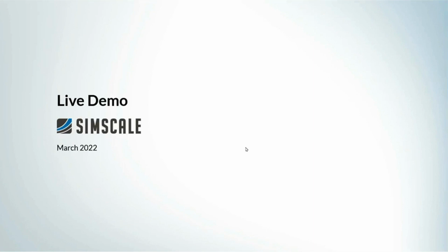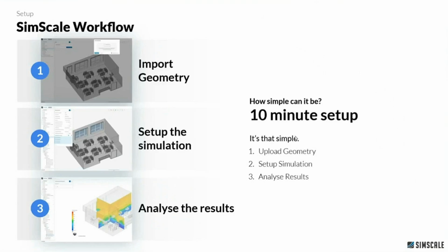For the live demonstration, we'll take a look at the SimScale platform and check how we can set up these kinds of simulations and analyze the results afterwards. Within SimScale, there are three major steps before you start the simulation, starting from importing your 3D geometry, setting up your simulation, which includes the boundary conditions or the inlets and outlets of the HVAC system, the heat sources, the concentration sources, and anything else that affects the physics of this particular simulation. Once these two steps are done, you can start the simulation and analyze the results.